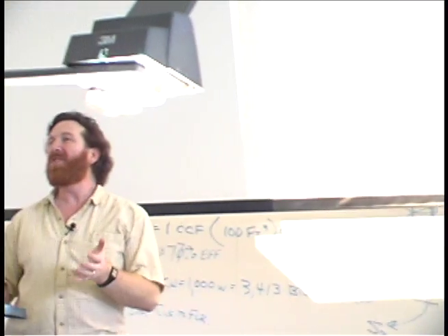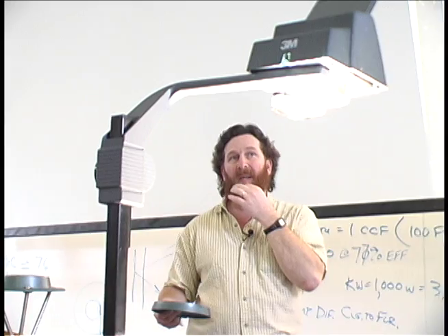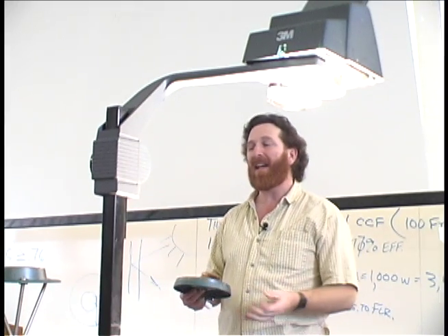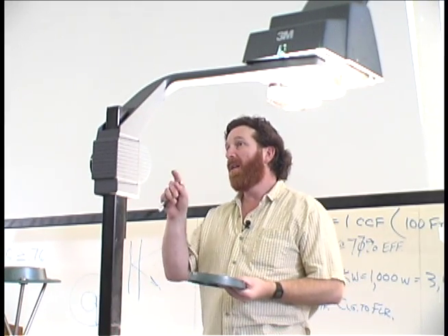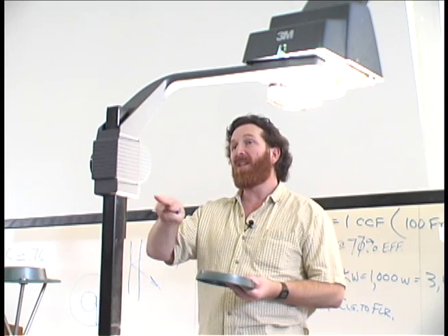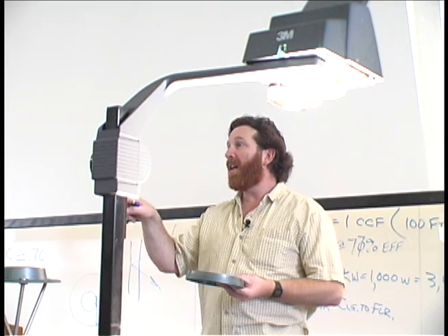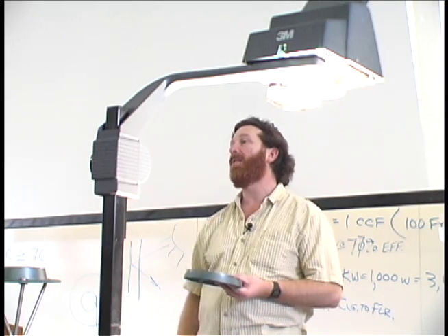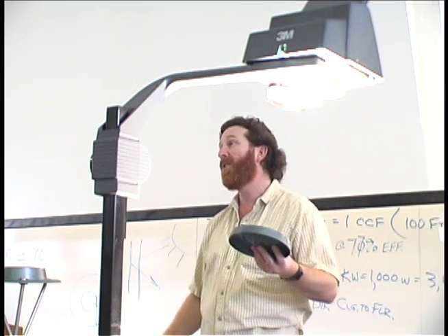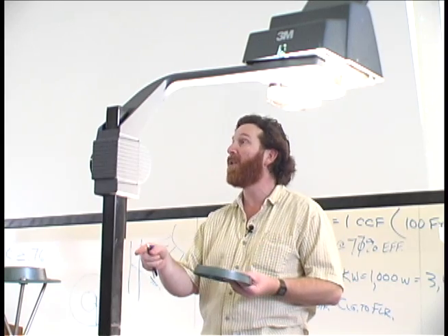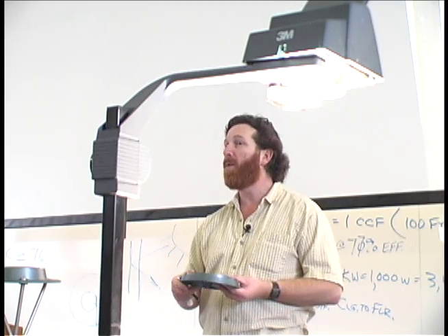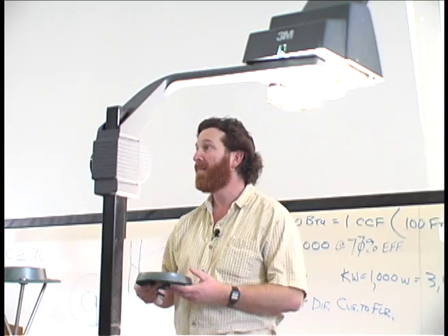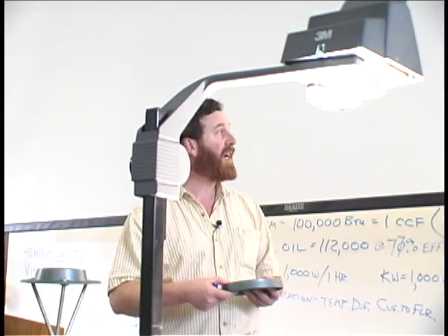The other way to find true south is a compass, which works okay, but actually the most accurate way to do it is look in the newspaper. Find out when sunrise and sunset are, and go out to the site halfway in between those two moments and put a stick in the ground and look which way the shadow's pointing, because that's solar noon. Doesn't matter what the clock says, that's solar noon, and that shadow will be pointing true north. And that's the best way to find out true south.